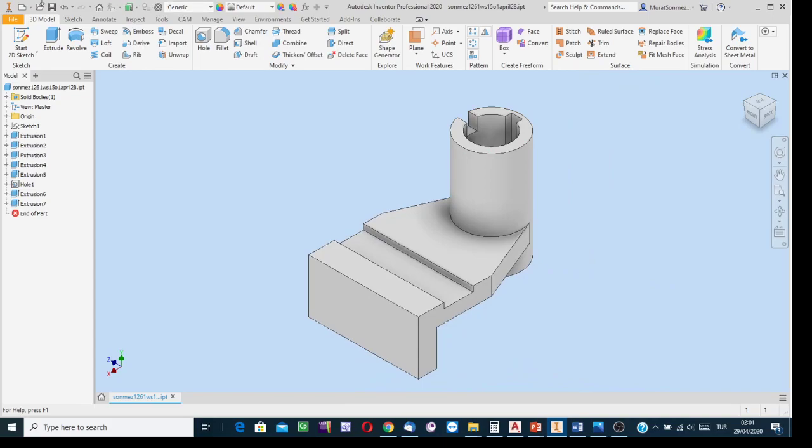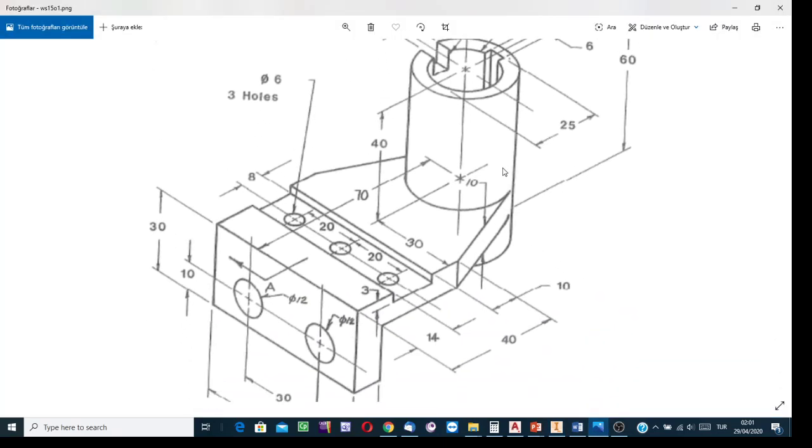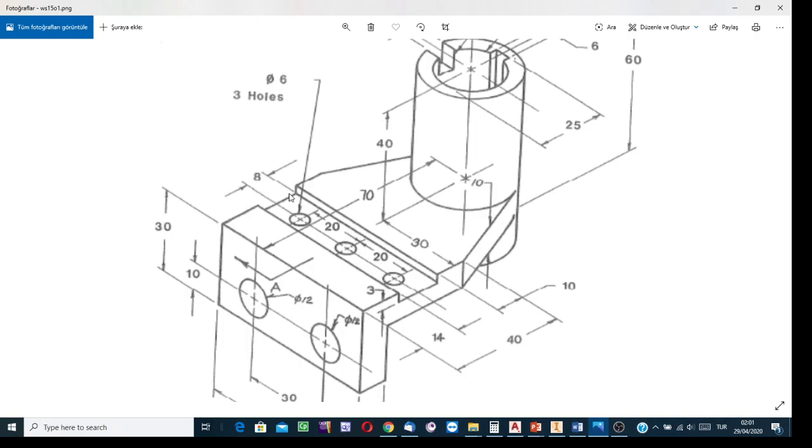The channels are okay. Clicked on save button. And then the last features to deal with are the holes. Here along the channel there are 3 holes. From the annotation I see that for all of them the size is the same, it is 6. Since in this hole annotation there is no depth value, this means these holes are truly extending holes.